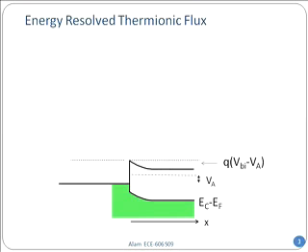So when you want to calculate current across this heterojunction, here the structure is such that the metal side has been grounded. The metal is on the left hand side, and you see I have just shown one line because that's the Fermi level inside the conduction band. I have not shown the edge of the conduction band, which is much below. And of course, even in metal, there is always a band gap, but that's farther down. So that's why we have not shown those things in this picture. You also know that there is a slight band bending on the metal side at the junction. That I have not shown as well. It's because the metal carrier concentration is so high, 10 to the power 20 per centimeter cube easily. So therefore, the amount of depletion and the band bending is minuscule, and has not been shown in this particular picture.